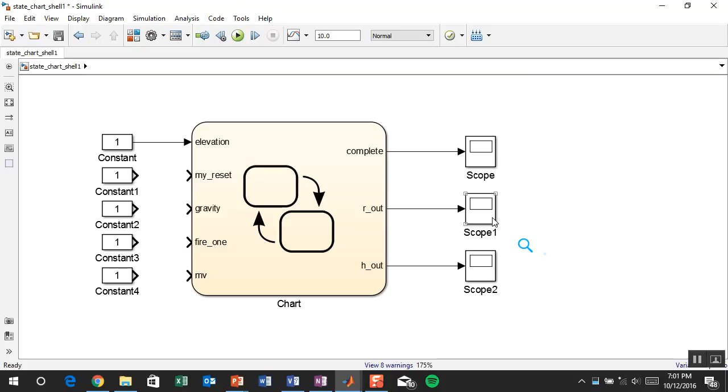So we need to take this model and figure out how to accelerate it. The problem is we're using the time solver inside Simulink. That's what we're leveraging here, right? So that we can have the automated zero crossing detection, so that we can use those continuous states and not solve so many things. So we kind of need to hack this a little bit. We want to represent the same thing. We just need to trick Simulink into solving it a whole bunch faster than reality so that we can get our solution faster.